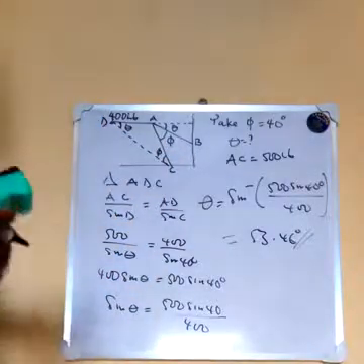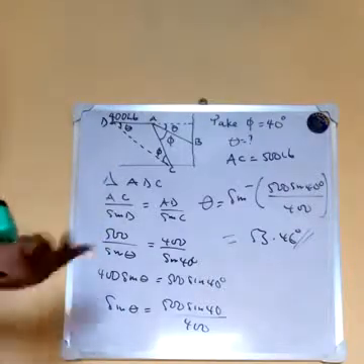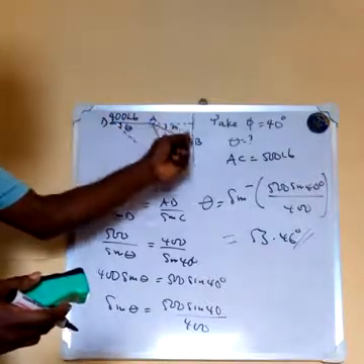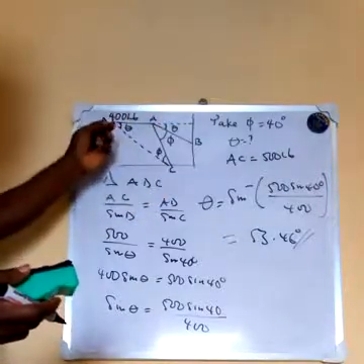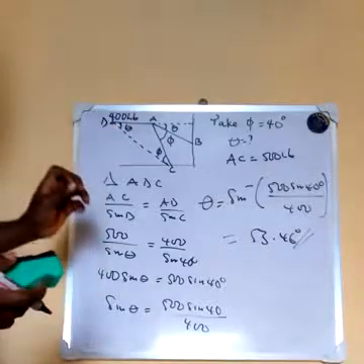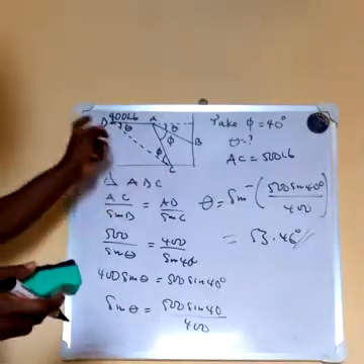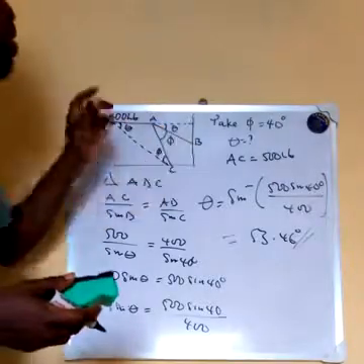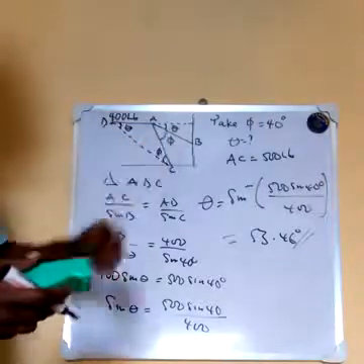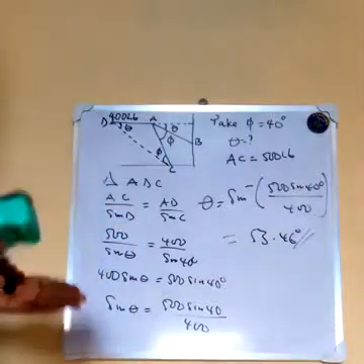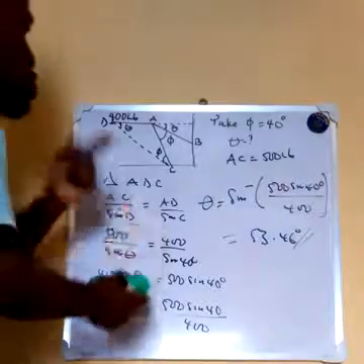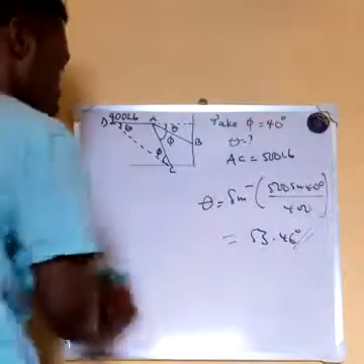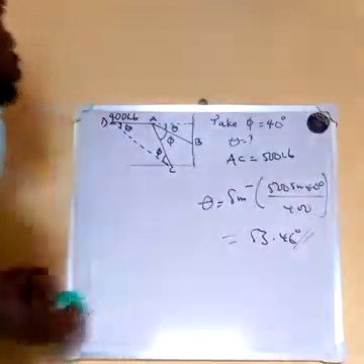Then from there, you can go on and get the component of force acting on member AB. So you can't do it from this direction. So you have to use this place. So you calculate the component of force acting on member DC. So whatever you have here is equal to that of a member AB. Why? Because this line and this line are parallel. So to do that now, you need to use cosine rule. Cosine rule is what you must use to get it.